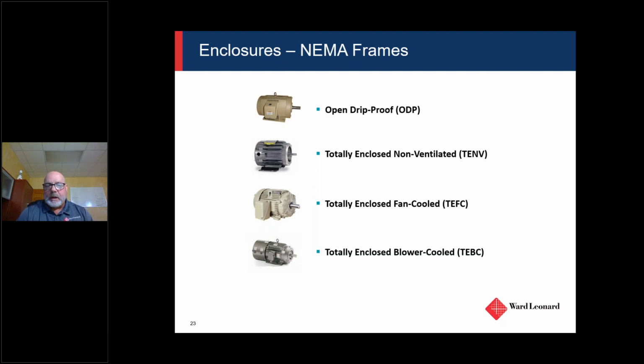So open drip proof, very common. That's one that, if it was an inside application or even outside, you really wouldn't put around a location that has a lot of ambient issues, meaning if it was a highly corrosive environment, if it's high dust, if it was out in the middle of a field somewhere where you had a lot of rodents and snakes and all that, I mean, they will find their way into a motor. So open drip proof runs really cool though. I mean, it's the best way to really do it, but not the best application for ambient conditions that are unstable, I guess I should say.